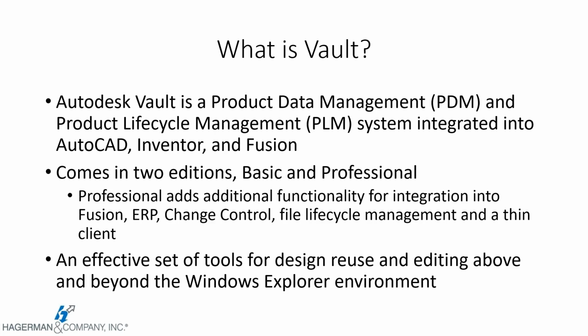Anecdotally, before I worked at Hagerman, I worked at a company where I was the sole Inventor user with a group of AutoCAD users, and I installed and set up a Vault Basic interface just for myself in Inventor to keep track of all of my parent-child relationships across fairly complicated assemblies that had a lot of design reuse inside of them. Being able to very quickly go in and mass edit an entire data set to apply properties to it, or very quickly check file references in the bottom up view, are things that Windows Explorer just can't do. It really can save you a lot of hassle and time working with your Inventor content or complex parent-child relationship content.